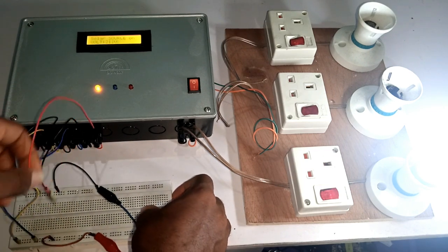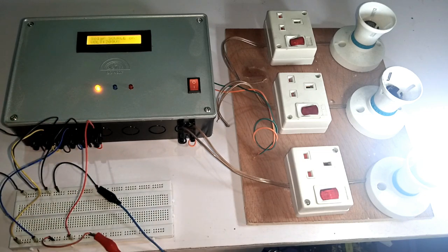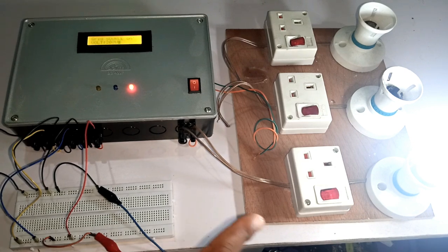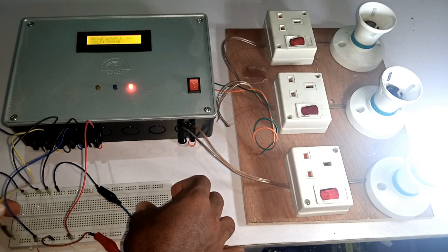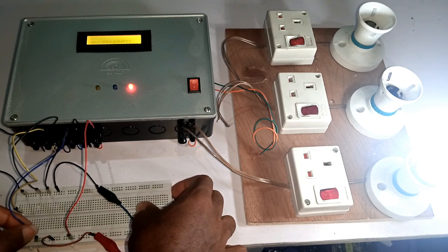Now, I am going to do the same thing for the red line, which I have as the grid line. The buzzer triggered again for 10 seconds and switched the load to the grid line instantly. To confirm this switching, I removed the yellow and the blue line first of all, and as you can see, the bulb is still on until I remove the red wire.